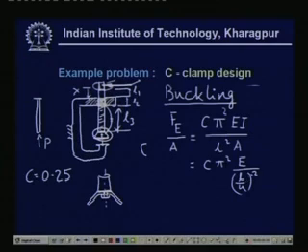But if L is very small compared to K, now I did not mention, this K is the radius of gyration, and this is nothing but the square root of I by A. So, this is the radius of gyration, and we have this formula, C pi square E by (L by K) square. Whenever L is very small compared to K, we can see that F E could be very high, but in fact it does not happen, because before it reaches a very high level, the material will be crushed, and we do not allow that.